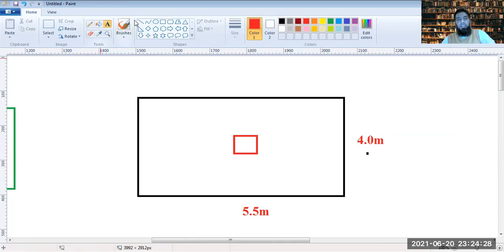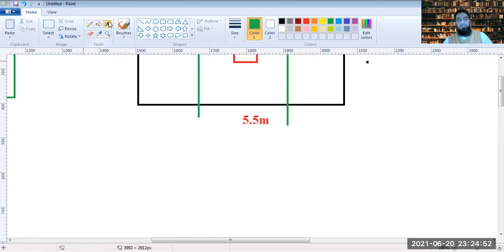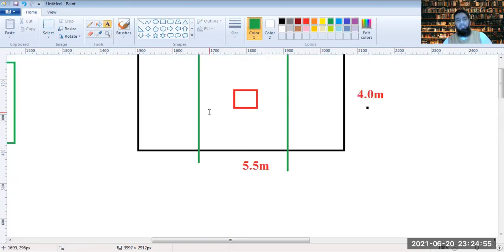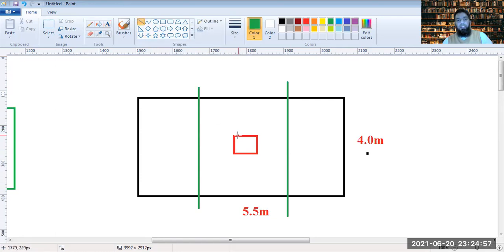Then the section at which the one-way shear becomes critical is at d distance on either side of this. Similarly on this side. Now, what is d distance? It's from the face of the column that it's at a distance of d. The face of the column is this.